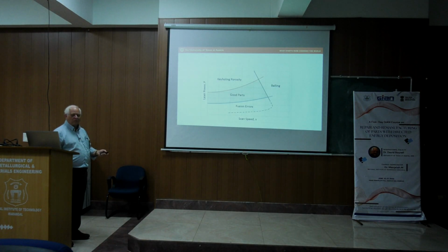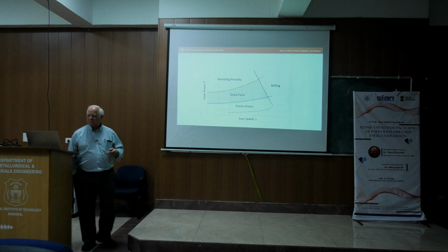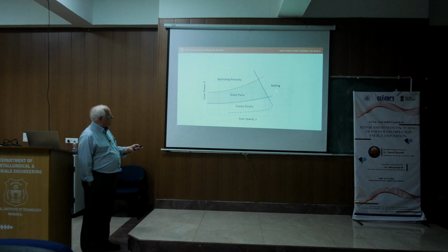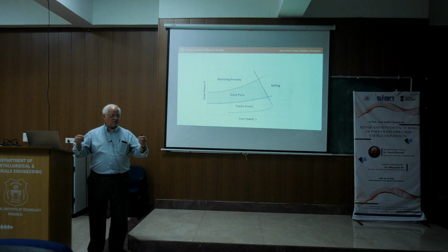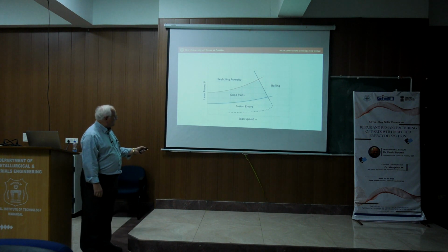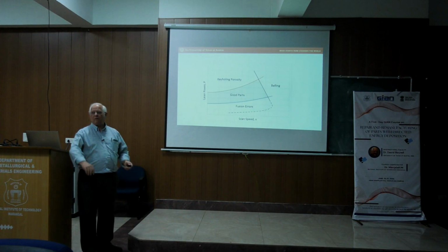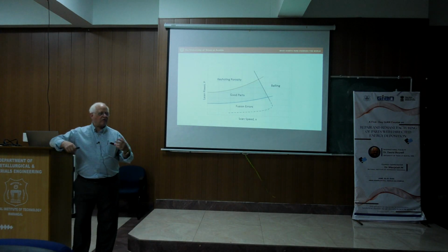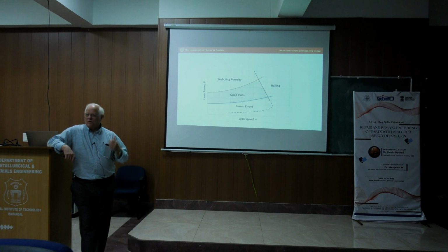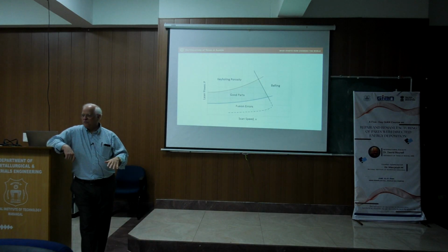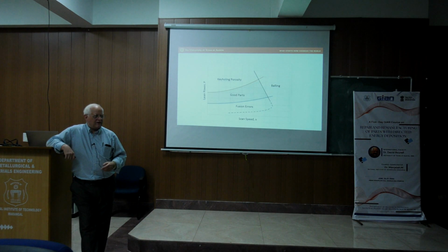I drew this. This is really new to me. Nobody else does this, because it really doesn't matter. But it turns out that the balling that happens out here is associated with this long melt stream that destabilizes. People have also observed balling in here at extremely low powers, and this is a different mechanism, but it's still a balling feature. The reason we don't care about it is because it's way below failure. It's like looking at a failure mode after another failure mode. Who cares? It's already failed. So why do we need to explore this?